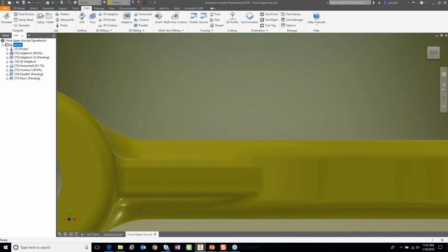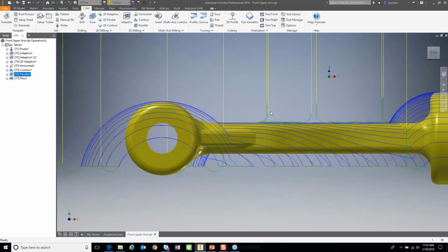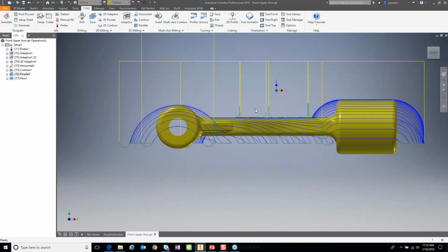So if you think of the tool path in the CAM window as being a process, the question is, does the process need to change because of the design change? And in this case, it does not. The same process we used will still work. We just need to update the tool path to the new part. The software goes and does that. It keeps it up to date for me. This looks good. We're ready to now save this part as a new design and to post-process and build new code. At this point, the CAM process is complete and everything's been tucked inside the CAD system.